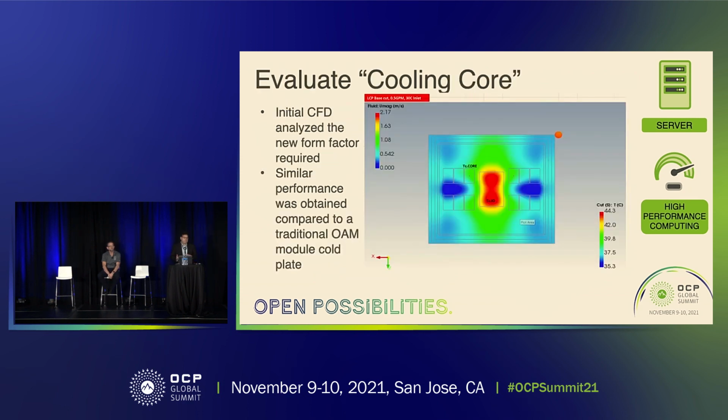The first thing we needed to do was look at that core, right? There's a lot happening with the main processor, with the memory, and the other heat generating components are just as important. But our focus is if we have the mesochannel core, the copper core for the highest performance right at that main chip, and because we have liquid and a liquid interface within the rest of the aluminum cold plate, we can use the gap pad solutions for bridging thermally onto the module.